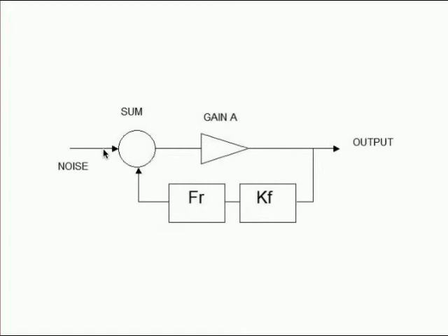But here we have got an input signal, and we know that the input signal will combine in phase with this signal coming back around the loop, within the bandwidth of the loop, because we've actually designed this oscillator so that this is positive feedback. So any input signal and this signal will add in phase within the bandwidth of the loop, of course.